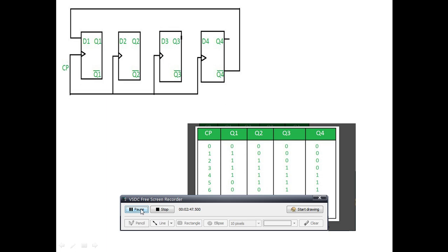So the next input of the flip-flop, the second pulse of a clock, is nothing but 1. See here, it is 1. So again, once here the feedback is 1. Once again, if the clock is energized, then the first flip-flop output is 1.